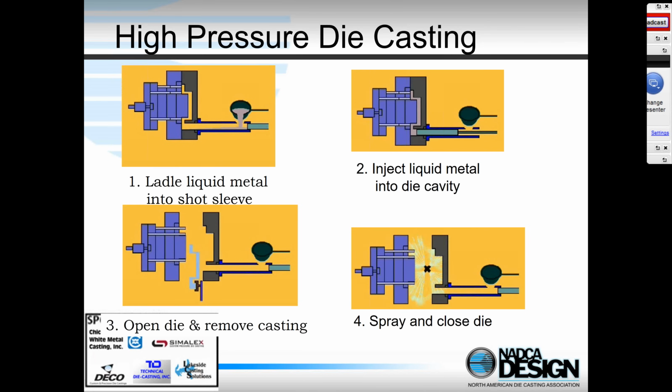Okay, so this schematic shows the die casting process. This is actually the cold chamber die casting process, and I'll talk about what that means on the next slide, I believe. Anyway, in stage one, we have the dies clamped closed. Maybe we're applying the 900 tons or whatever clamping load to those dies.